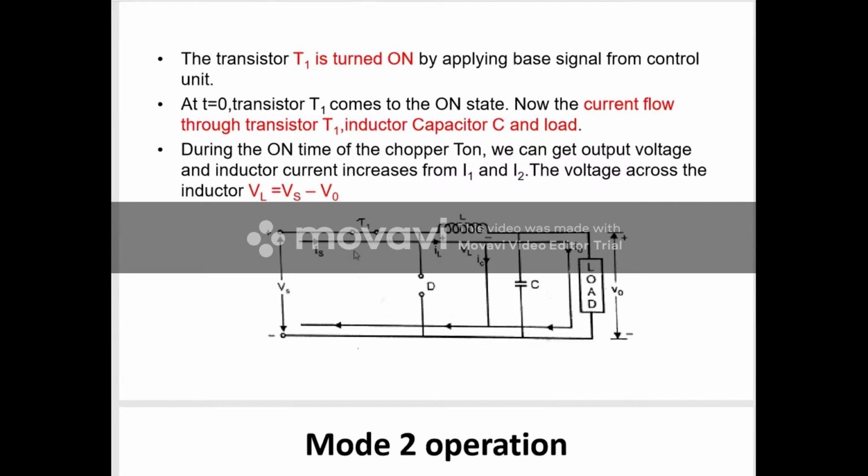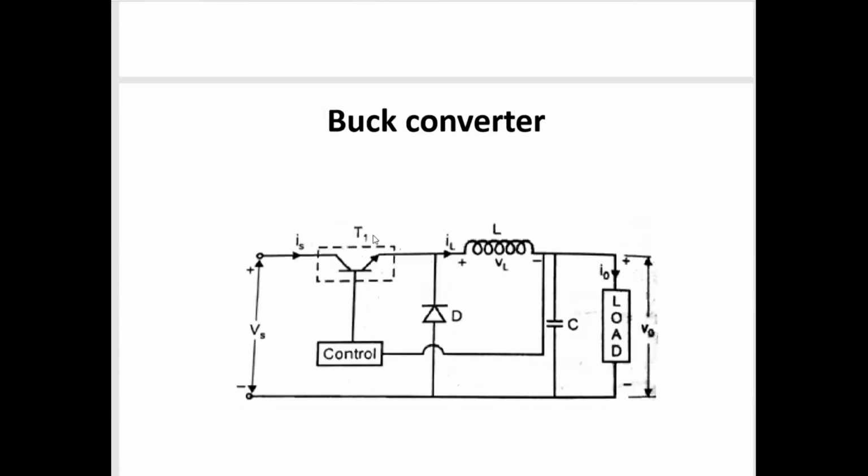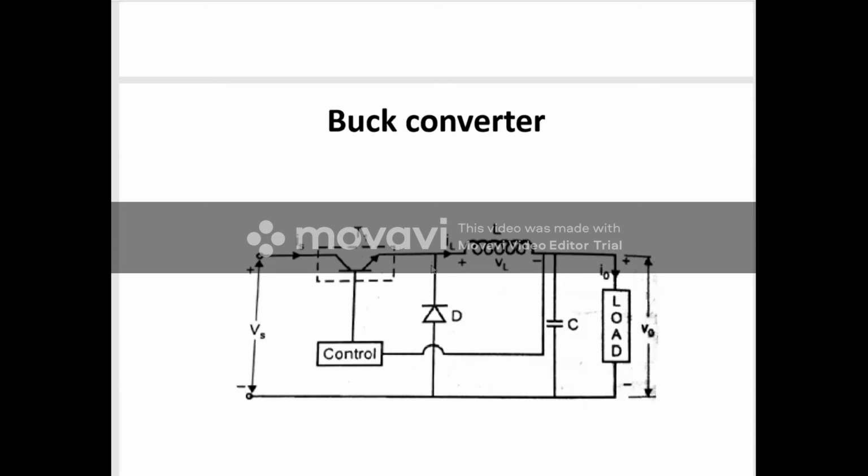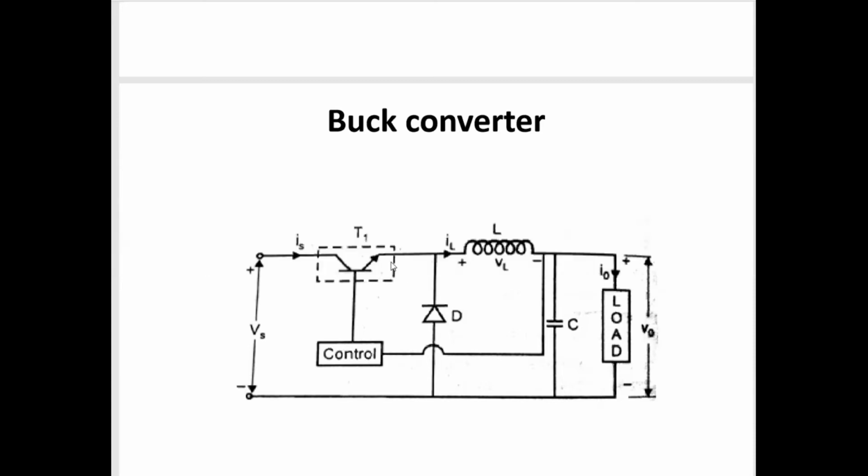So this transistor is in closed position. If this transistor is in closed position, what about the position of this diode? You see the diode anode is connected to ground, and the cathode is connected to here. So this diode is either forward biased or reverse biased. During this short circuit condition, the input voltage Vs that we apply comes directly here.